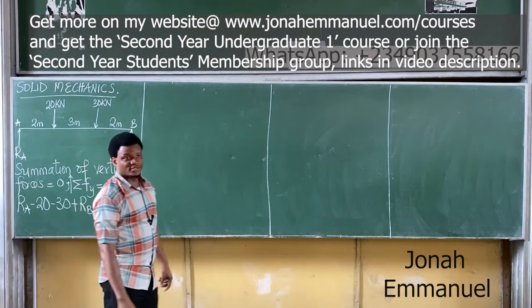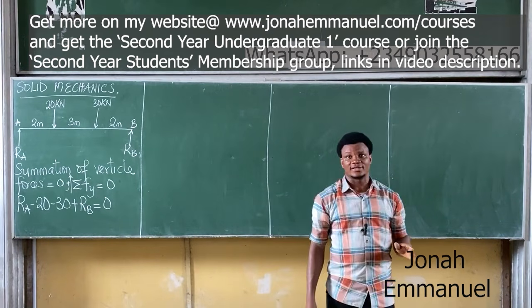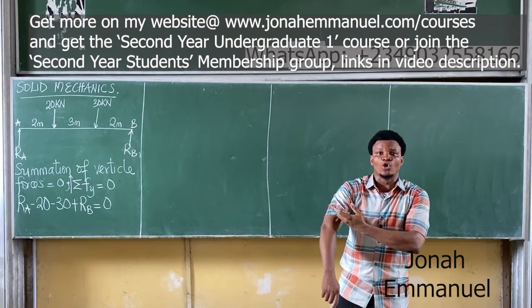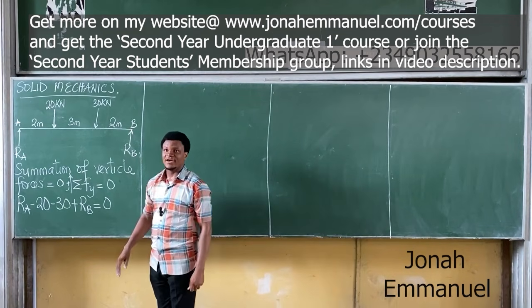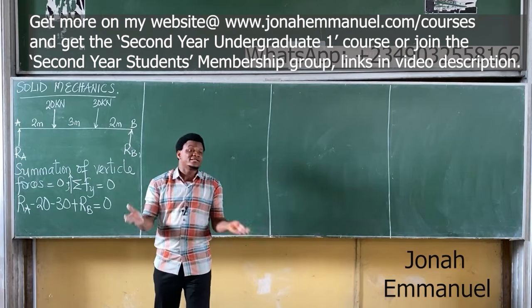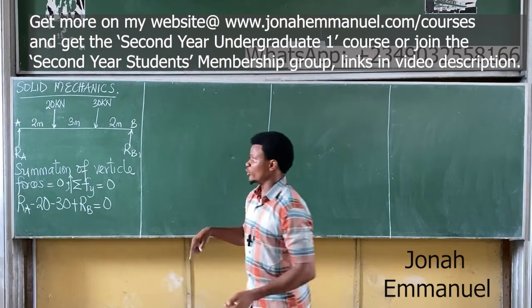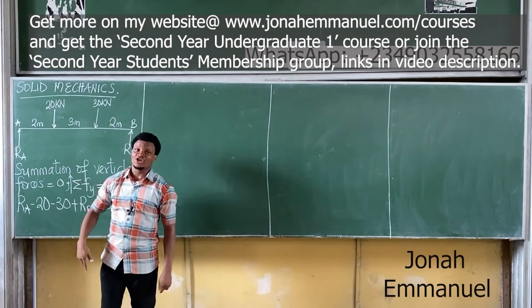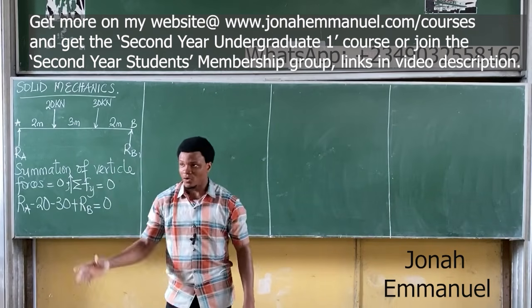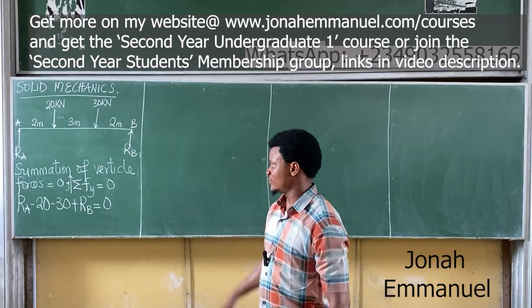It's equal to 0: summation of vertical forces equal to 0. It's going up, positive. It's coming down, negative. Some authors do the opposite. Some authors will say if it's coming down, positive, and if it's going up, negative. You still have the same answer. So depending on your author, try it that way. We'll have the same thing. But for me, I'm going this way, please.